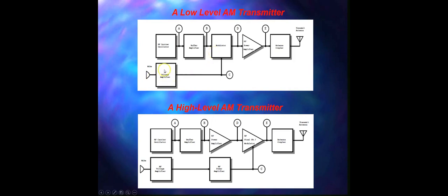So a voltage amplifier is basically used to boost the microphone's signal, and the signal level at the output of the AF voltage amplifier is usually around 1 volt RMS, and it is highly dependent upon the transmitter's design. You also notice that the audio frequency amplifier in the transmitter is only providing a voltage gain, not necessarily a current gain for the microphone's signal. The power level is quite small at the output of the amplifier. It will be around a few milliwatts of power.